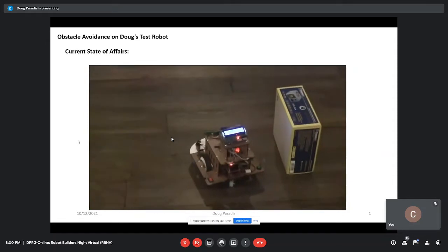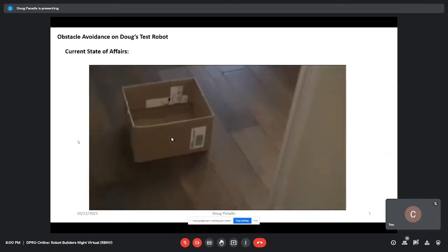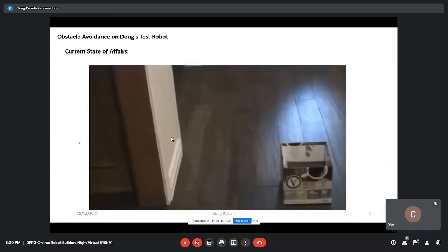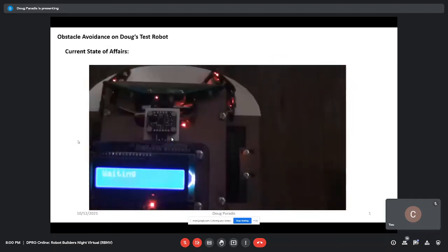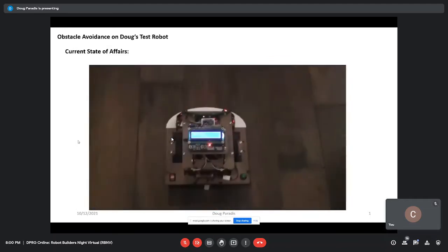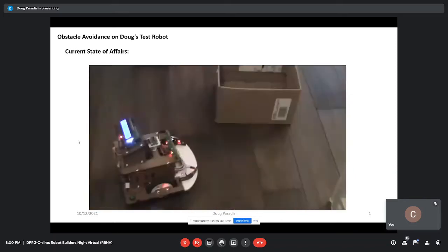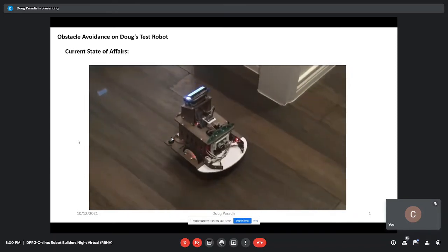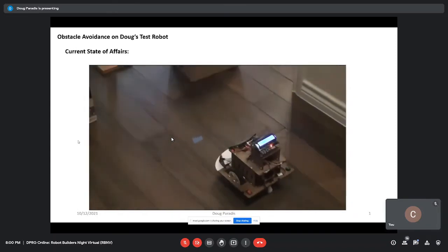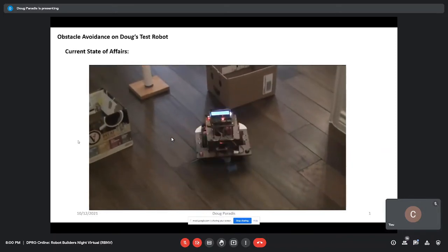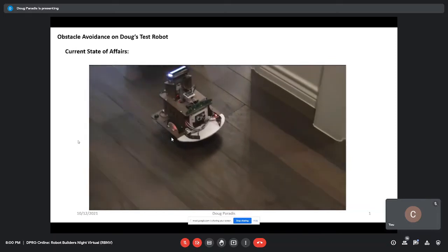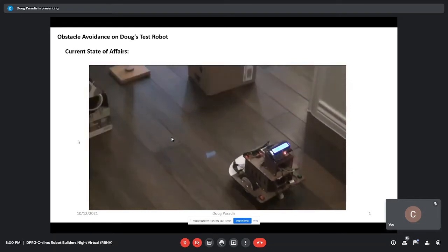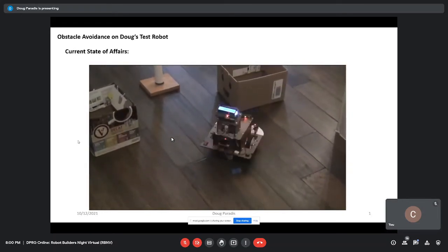So now I've decided to try to make it fail. So you notice I've moved the 2 boxes up close. So it's really kind of trapped. I mean, in theory, it could go around that one box on the left, but let's see what it does. And here you see that classic problem that David was talking about. I'm going 180 degrees from the target, so going back towards the target because my temp waypoint didn't find any obstacle. And I'm just going back and forth, okay? I said, well, maybe it'll oscillate its way out of this thing. But the answer is no.